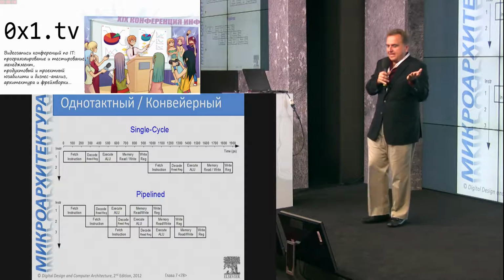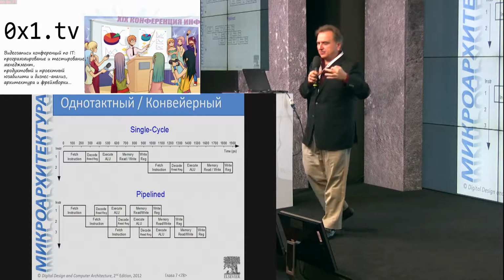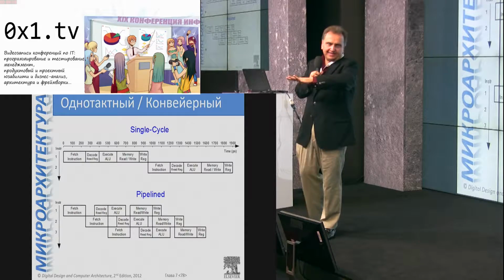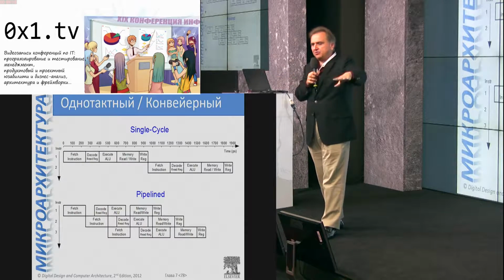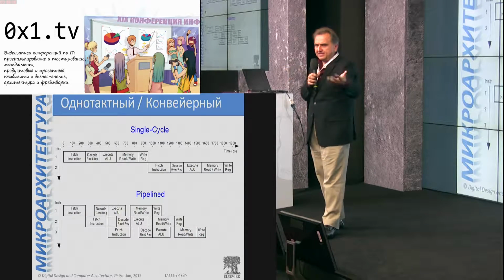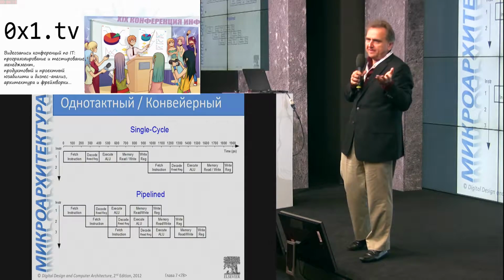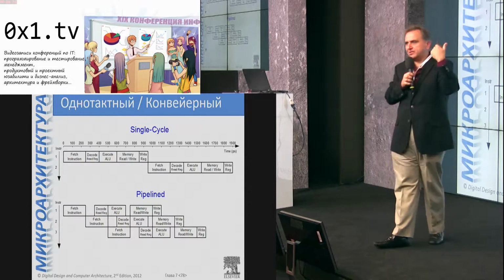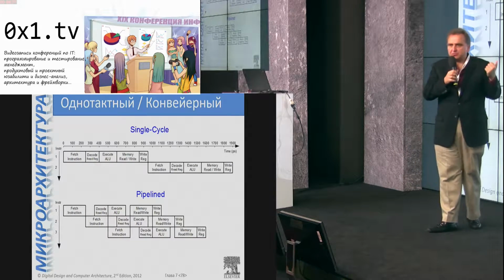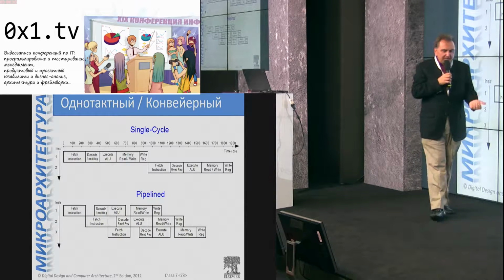And after that, a special software will turn this description into this picture, and then place and route happens to it. It will have several technological steps to give you a file, GDSII, that goes to the factory that builds a processor.